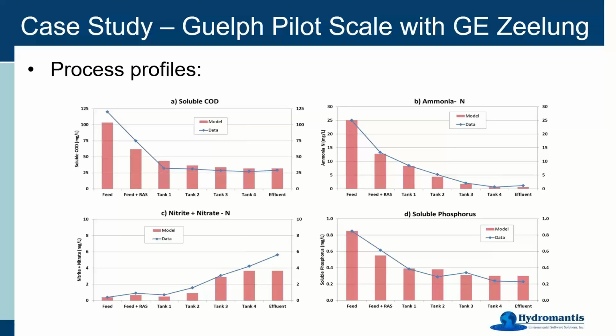If you are in the process of trying to calibrate a system for denitrification, it's always important to make sure you have good characterization of your influent, to make sure you have the right amount of available carbon that might be relevant in your particular case, as it was here. And actually the ammonia fit very, very well. That part we hardly had to touch at all. And once we got that soluble carbon calibrated and our influent characterization, our denite snapped right away.